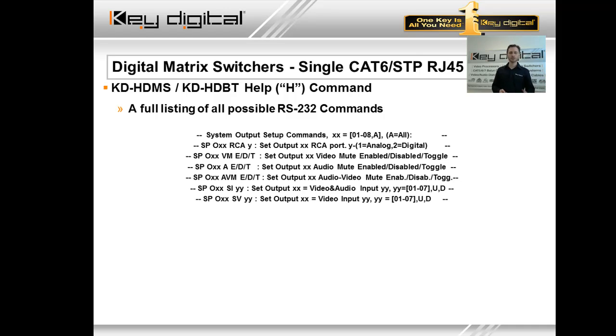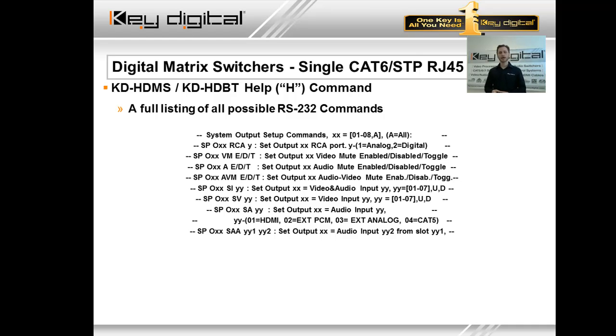We have a switch video only command, the SV. We have a switch audio only command, the SA. Now remember, with the audio there are some variables, aren't there? This SA works in harmony with the SV and SI commands. So if you've already made a switch using SI or SV, now you can move within that location using SA. It's a way that achieves this in a two-part sequence. Or we have a way that achieves it in a single-part sequence, SPO XX, that's your output number, the XX, SAA,